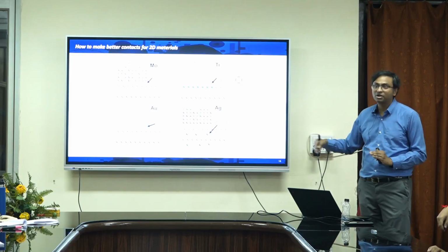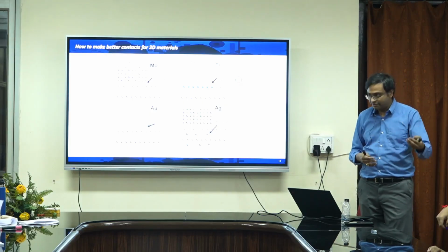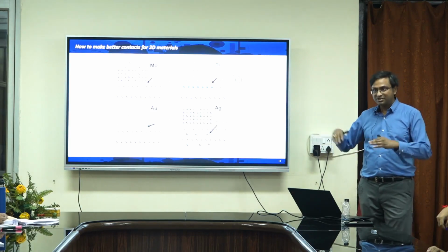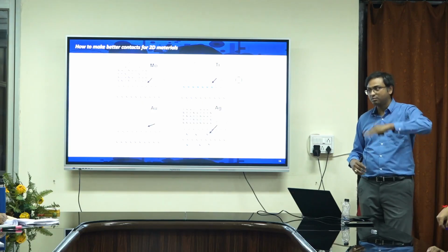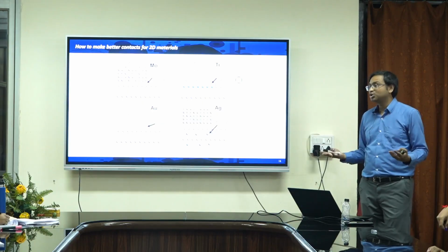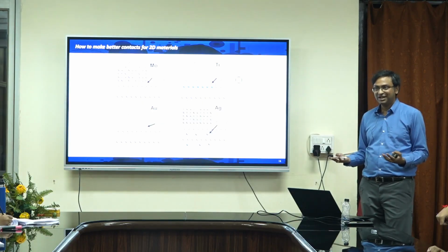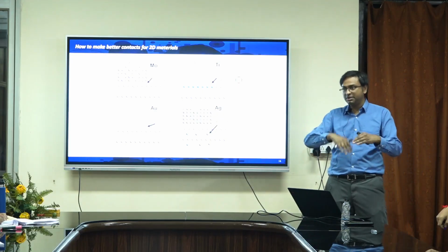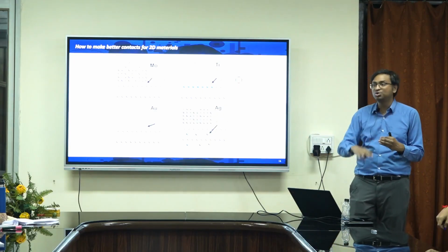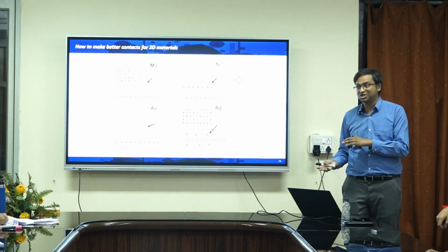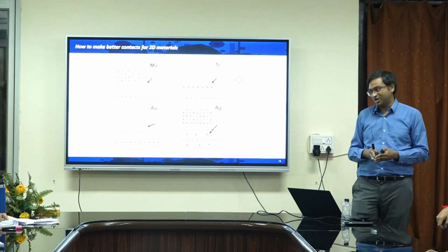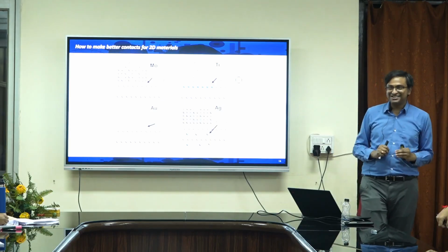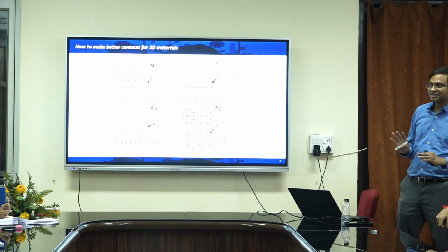Metal-2D interfaces and metal-semiconductor interfaces are very complex. There is a lot going on, because when you are depositing, whether using sputtering, e-beam evaporation, or thermal evaporation, it all matters, because the energy with which these metal particles bombard your 2D surface also changes the contact resistance. And even if you stay with the same tool, say e-beam evaporation, how fast you do the deposition or what the vacuum condition of the tool is will also impact your contact resistance. So contacts remain a big challenge in the field, and so much fundamental understanding still needs to be developed.